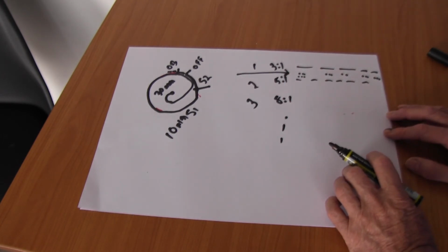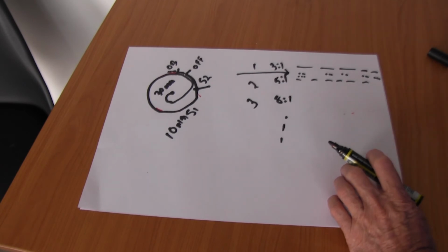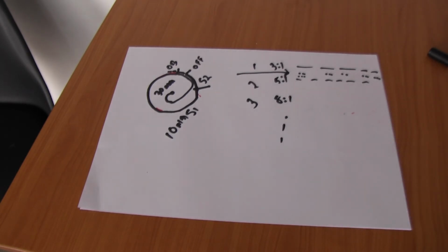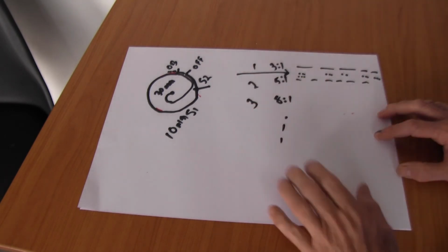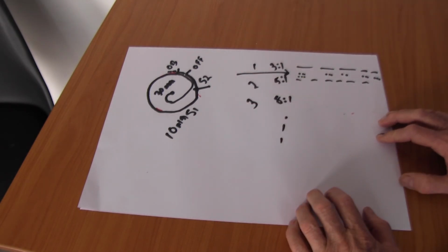So in this way we can create a very powerful hole technology in a high definition plasma cutter, say from the likes of someone like Hypertherm. They will have all the smarts built into their CAM system, which I think they call ProNest. But LinuxCNC doesn't have a CAM system. It doesn't have a post processor.